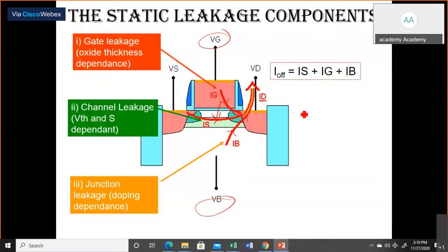because we are talking about nanoscale dimension, right? If we talk about an electric field of 1 volt, let's say, and the dimension is 10 nanometer, see how much electric field there is: 1 volt divided by 10 nanometer. Ultimately it comes to megavolt per centimeter, which is a very huge number. Because of that, tunneling of carriers is possible, and this tunneling of carriers will lead to a gate leakage current in a MOSFET.